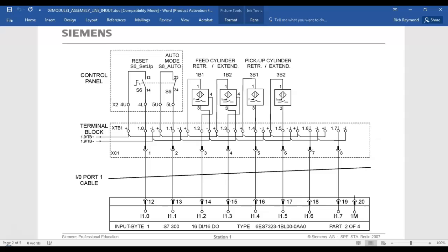So we are putting together some boxes. They're over there in the other lab. I need to bring them over here, where we're going to actually let one class wire the PLC. But the problem is the PLCs are set up for sinking, and the person that bought the inductive sensors bought sinking sensors. So you got a sinking sensor hooked up to a sinking input. So what's going to happen? But it wires up the same.